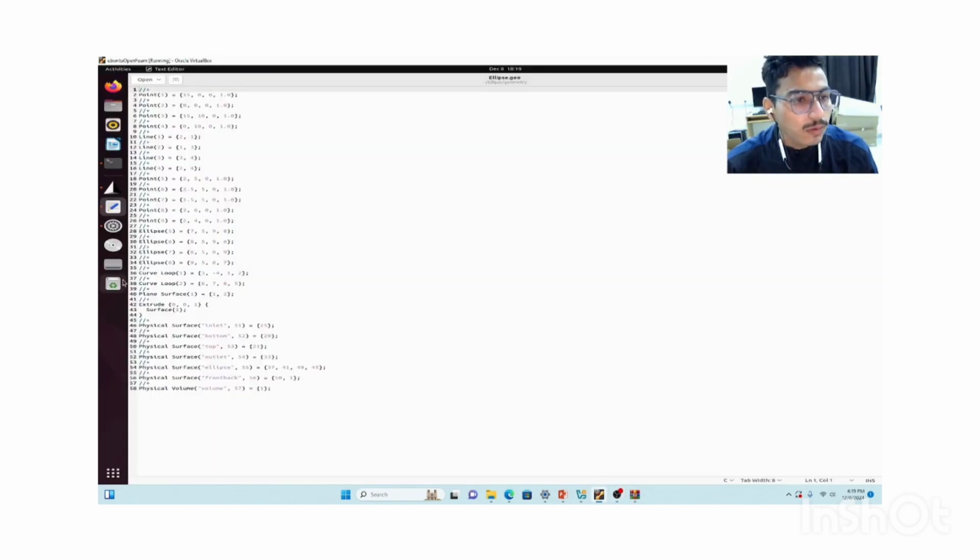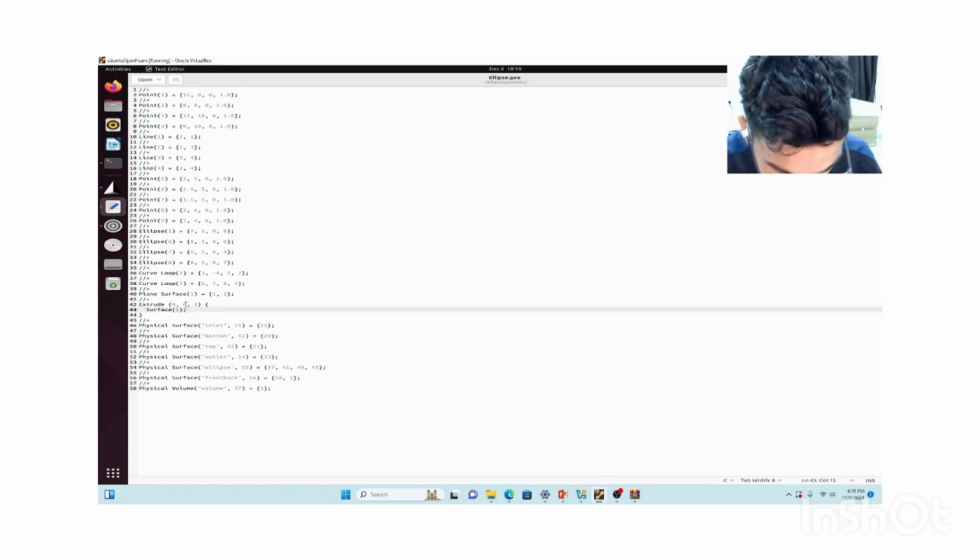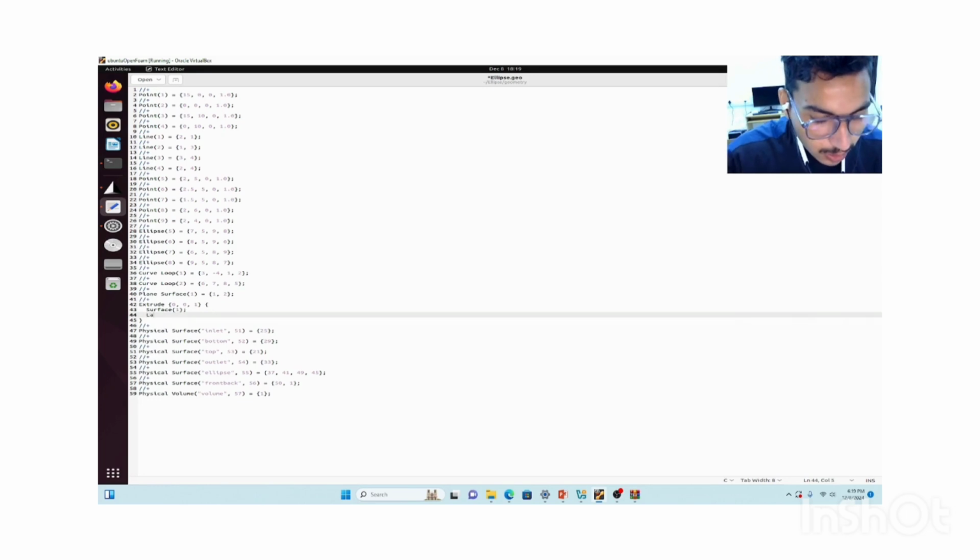So one more thing we had to do, that we had to first make another, that is layers. This is used for the extrude element, and layers in curly brackets, and here it is 1 in the extrude, that is thickness 1, so only one layer will be used.